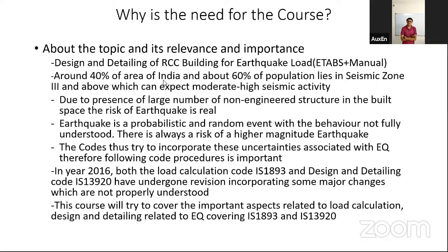So during this course, we will emphasize both these codes. We will try to do it manually, plus we will try to do it on ETABS also. If you are using any version of ETABS other than ETABS 18, the new codes have not been incorporated. Understood? If you want these new codes to be incorporated in your ETABS, you have to use ETABS 18 and above.